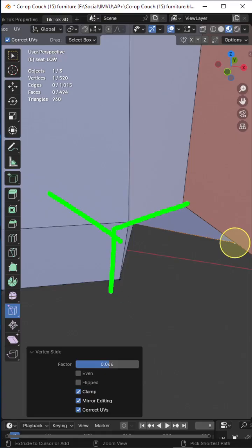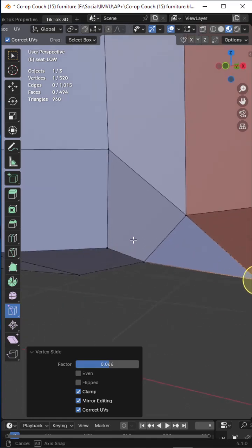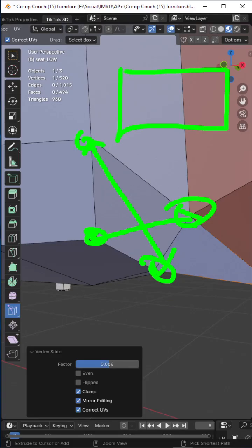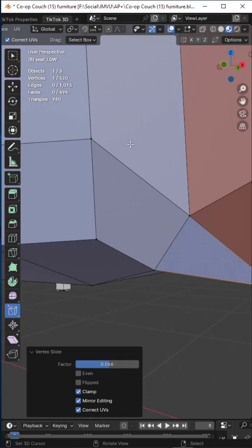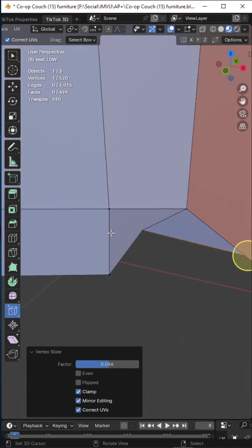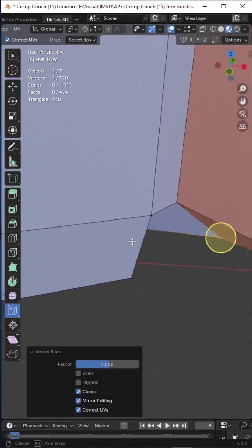It collapsed on itself, and that's because of the edge alignment between these two vertices versus these two vertices, so we have the option of this triangular edge that makes up a square face. It can either go in that direction or it can go in that direction, and when it's over a curve or around what should be a curved shape, it can collapse on itself.